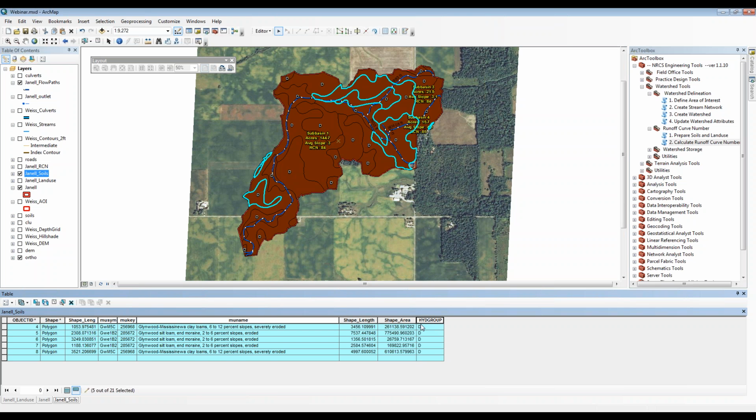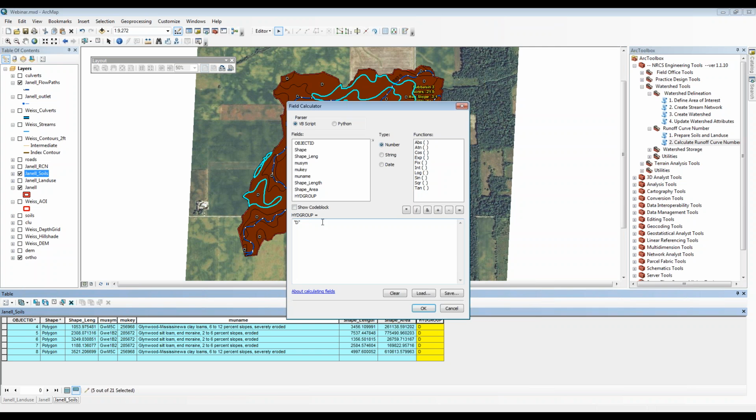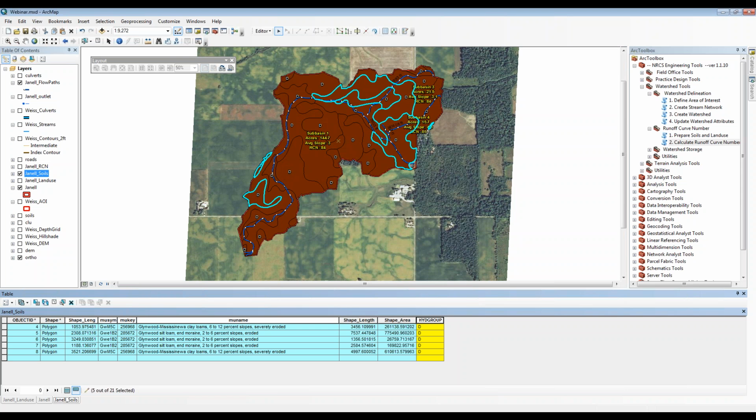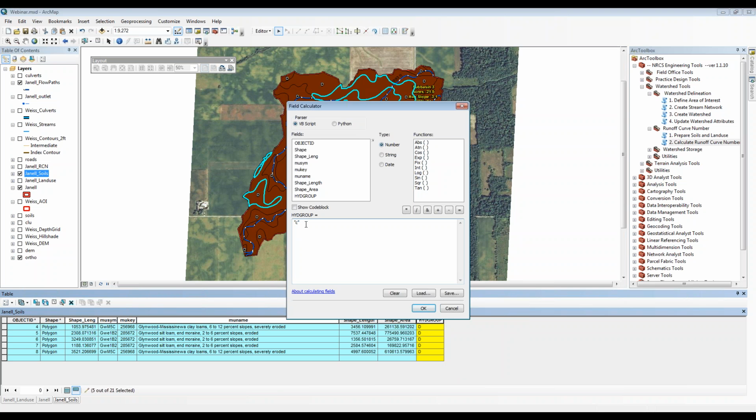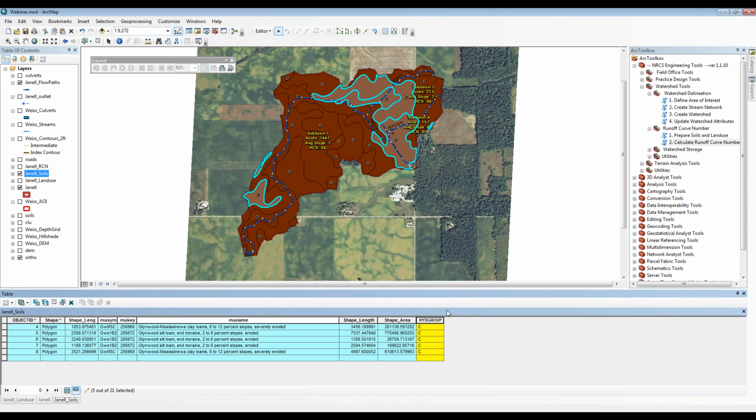And we can do the same thing for the land use. If you want everything to be good, but don't want to have to hit the drop downs and say good on everything, you can just right-click, go to Field Calculator, and type in "good". Make sure you put it in quotation marks. Whenever you're using Field Calculator, if it is a text value, it needs to be in quotation marks. If it is a numerical value, you don't need quotes, but we only have text in my example, so we need quotes. Boom. And just so that you know that this works, we're going to make everything C so you can see that it will update to something different. Bam. Okay. Any other things that we should do?